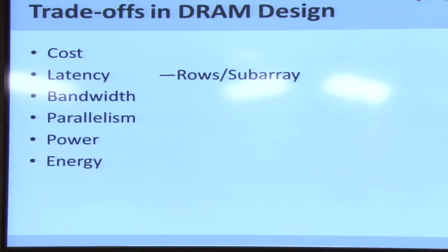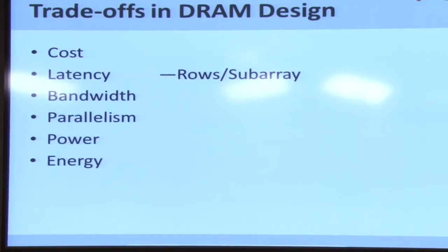So today you may have heard of DDR 1666, right? 1666 megahertz is, and again at four clock cycles is, if I'm sending data at each half cycle, it means the actual frequency is 1666 multiplied by 2, and DRAM internally operates at 833 megahertz for the technology, right?